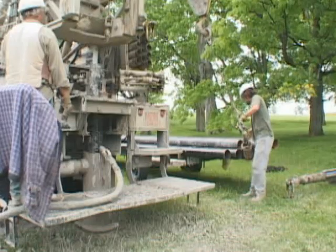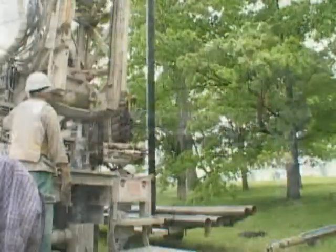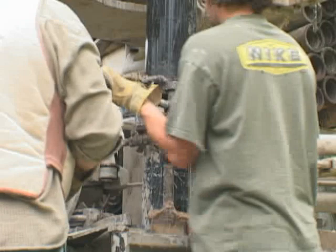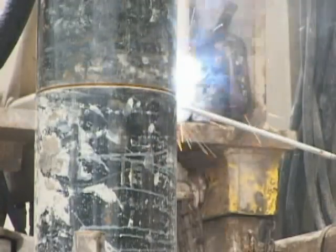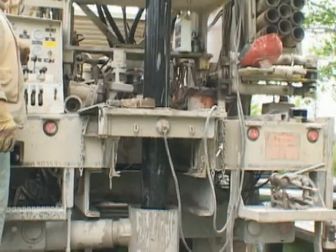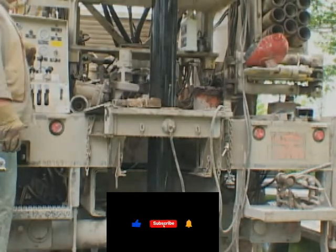Safe workplace procedures always entail the use of caution when working around heavy or rotating equipment. Never place yourself between something that moves and something that doesn't. Casing liners ensure casing sections are square to each other. Beveled joints provide for maximum weld penetration. After completing casing and screen installation, the hole is grouted and developed to a sand-free state as per Regulation 903.